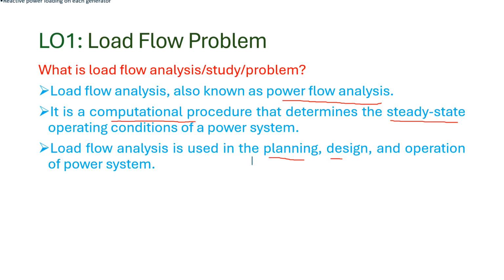Similarly, for the purpose of design, if I want to lay one transmission line, what should be its operating voltage? What should be its power capacity or line current capacity? All those aspects we can design using this load flow analysis.